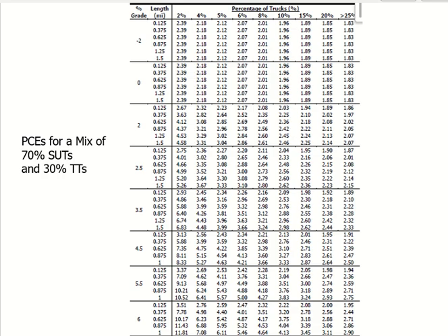Now, going back to the point of negative gradient. You don't have minus 3.5% here. You have only up to minus 2. So now you're going out of the range of the table, right? What did I say in that case? You take the last value you have in the table. So forget about the gradient. 1.25 miles length and 10% trucks. 1.96.